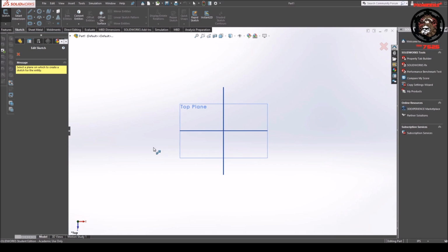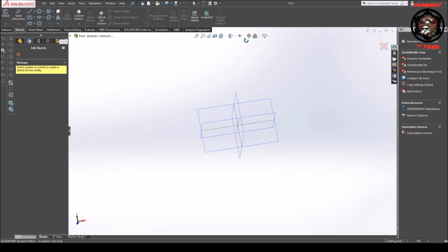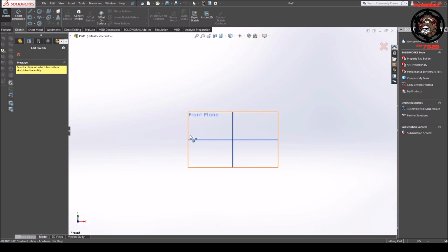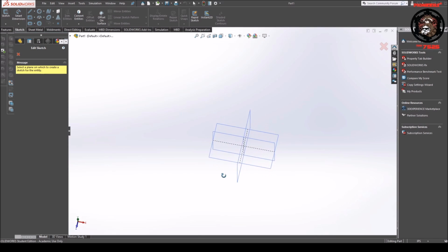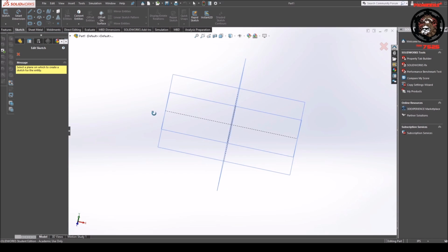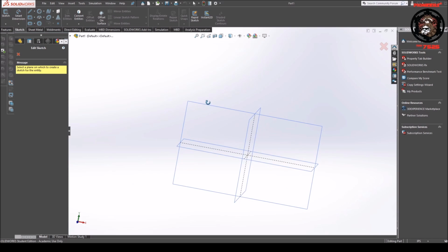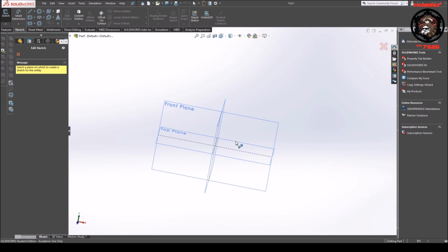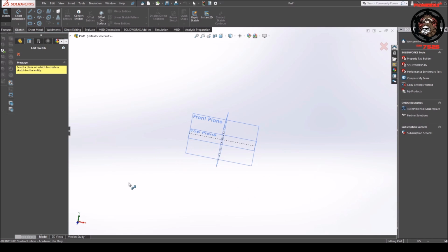However, if you're running a 3D printer, for example, you may want to design your parts as if the top plane was the front, because that's where your Z-axis is. On a 3D printer, or a CNC mill, if you want to machine something, you need to understand that the positive orientation is upwards in the Z direction.